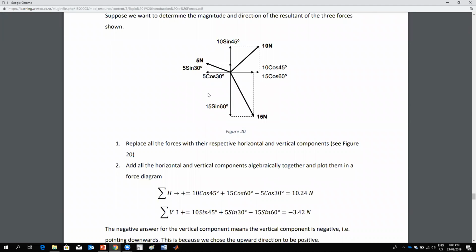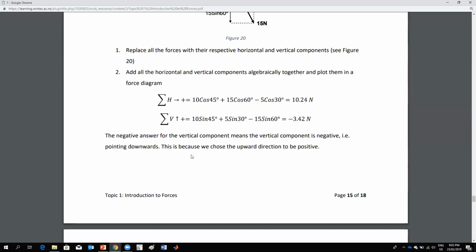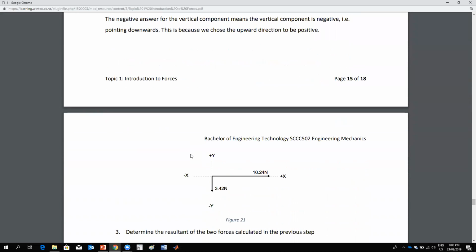And we discussed what happens if we have more forces added. As force is a vector, where the first force stops, we continue with another arrow and add it, or it could go in the opposite direction as a negative. So we always use algebraic summation of forces in one direction, and we subtract in the other direction. We need to know the positive and negative. The summation of forces in the horizontal is represented by H, and the summation of forces in the vertical by V, and you can find the components for that.